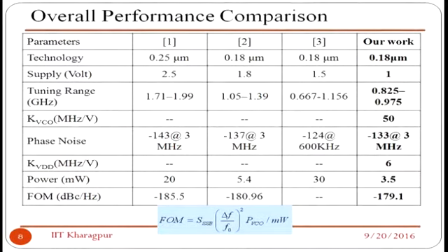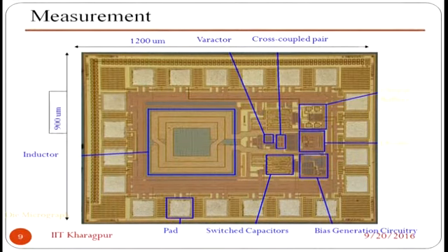I am not up to that simulation. All the measured data I will show you, just wait. After the design and simulations, you remember it's a pretty old design, so large area, 180 nanometer process. This is the tank circuit, the inductor. You can see that it is almost 3.5 turns, and then you have the varactor and this cross-coupled pair, and this is 1.2 millimeter by 1.2 millimeter. Nowadays people work with a complete transceiver in 1.2 millimeter by 1.2 millimeter.